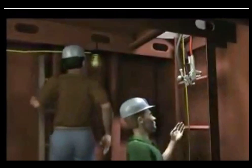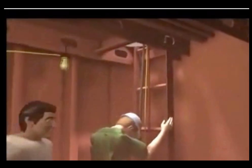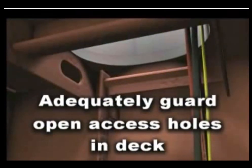Although not contributing to the fatality, electrical cords and open access holes presented 2 additional safety hazards. Electrical cords and painting hoses should not be in the way of workers using the ladder. Clear interference with ladder access as much as possible. Open access holes and decks should be adequately guarded to prevent employees from accidentally falling down them.